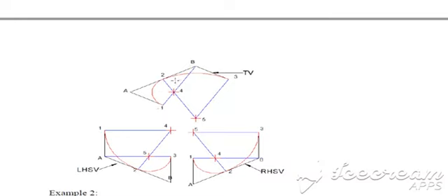Follow the same process wherever you want the semicircle. Similarly, you can go for the quarter circle. Just find these 2 points and draw the perpendiculars wherever they will intersect. With that point as a center and distance till the midpoint, mark an arc. Or if your semicircle is on this side, repeat the process. Draw the actual perpendiculars from the corner points. With this point as a center, the distance till the perpendicular as a radius, mark an arc.